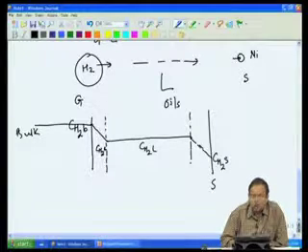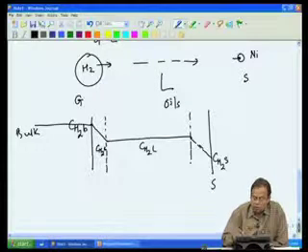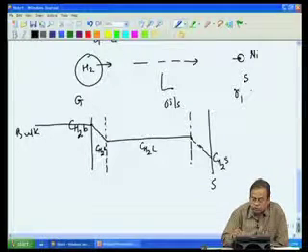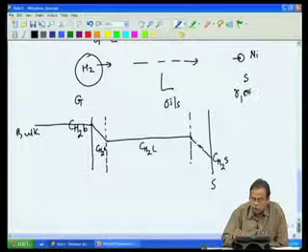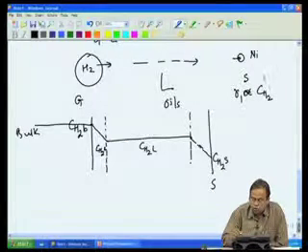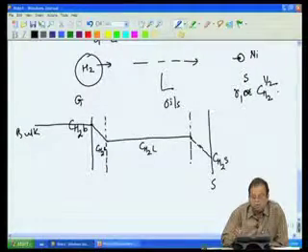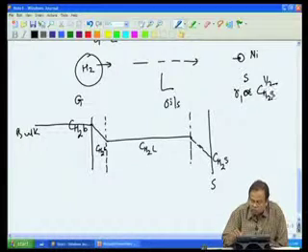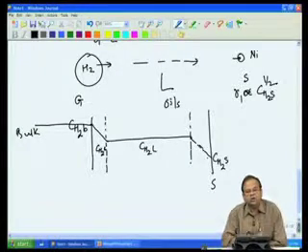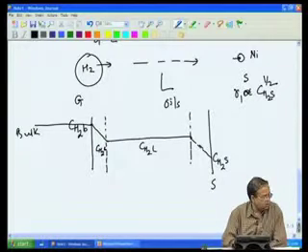Now, all the kinetics that we wrote, that is R1, R2 and so on, we said R1 is proportional to CH2 raised to half. That concentration must be the concentration on the surface of the catalyst. Now, here once again we are going to make another assumption.